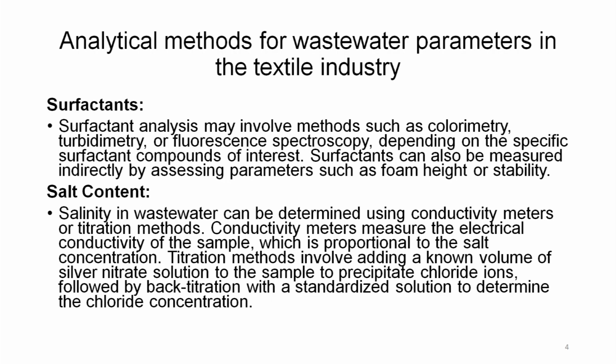So, there are methods very well defined for the analysis. For COD, there is an oxidation solution of dichromate and permanganate. For BOD, there is a 5-day test at 20 degrees. It is allowed to incubate and we see how oxygen consumption is taking place.